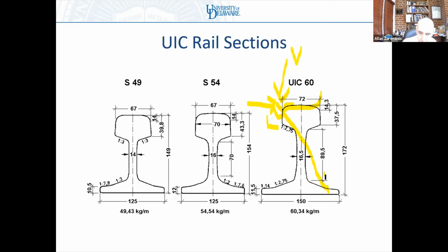I want my base of my rail to be such that the vector resultant of the L and V as much as possible falls inside the base of the rail. Why? Because it's stable and will stand up by itself on the traffic. In 90% of the applications, you can actually remove fasteners and the rail will actually stay stable by itself because the vector resultant will not go outside of the base of the rail. The problem is in 10% it will, and that's where you need your fasteners.